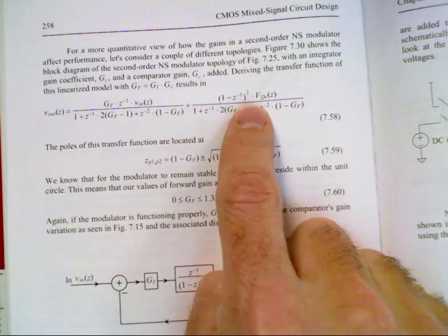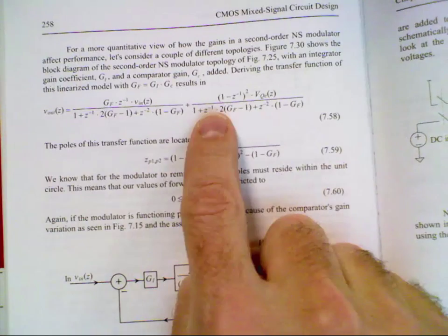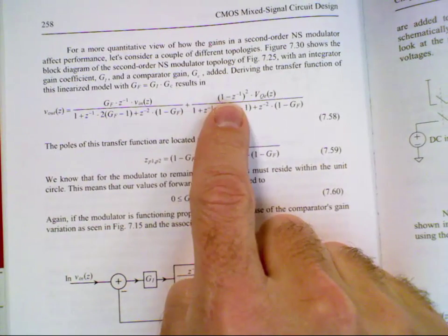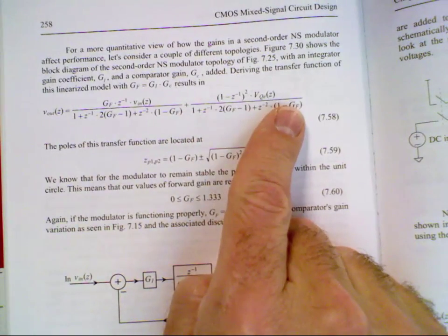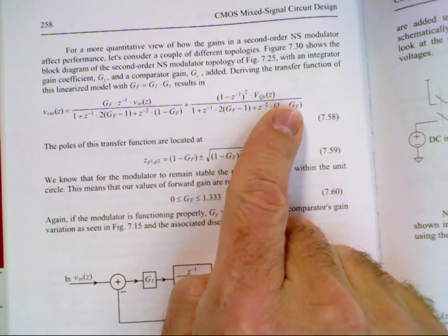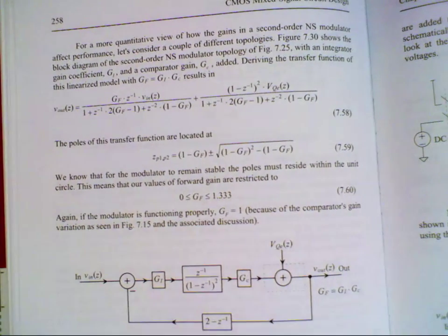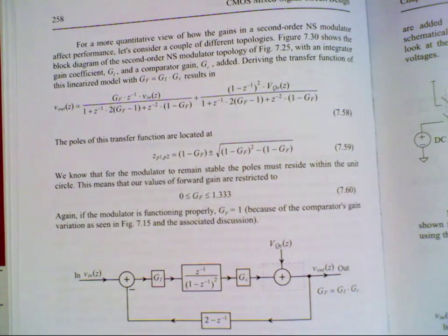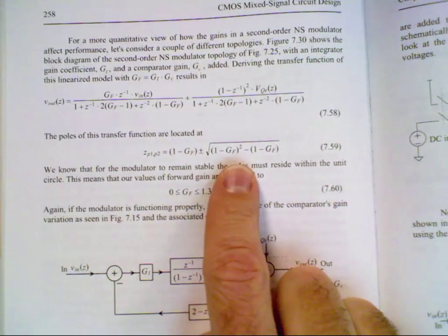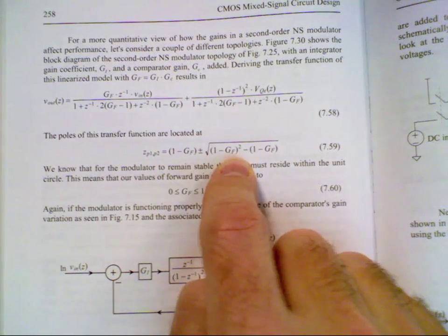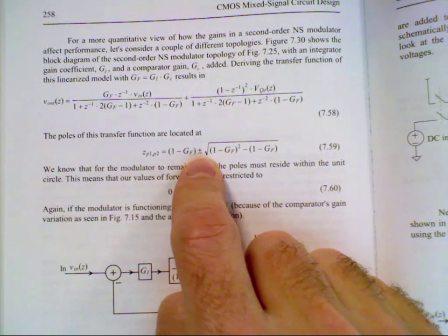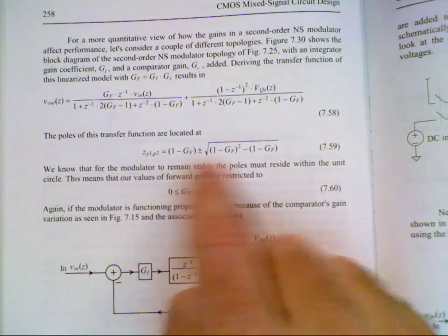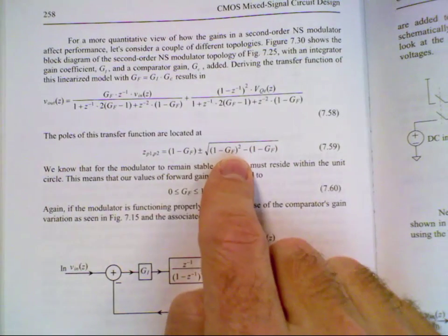And then if I look here, the bottom goes away, except for the 1, and I just get second order differentiation. And so then I ask, all right, where are the poles located? Does everybody follow that? So my forward gain is going to go to 1, and then it's going to operate properly. Where are the poles located? What's that? No, well, yeah, ideally they're at the origin, so you just get delay.